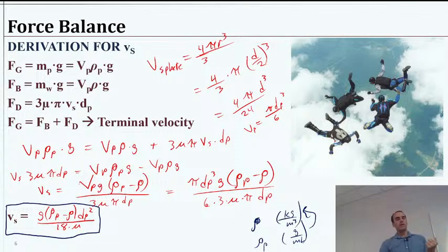So if we can change the density, or the viscosity of water, that could be a thing, right? On the denominator here, if we decrease the viscosity, that'll increase the settling velocity. So particles will settle faster through water than through honey. And you kind of know that already. Didn't have to tell you. We could make the particles heavier, or more dense, rather. That would have some impact. But probably the easiest thing to do would be to go to Jupiter. No. So we could maybe change the gravity, right?